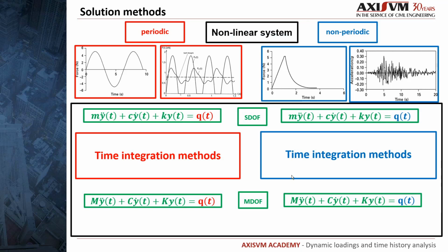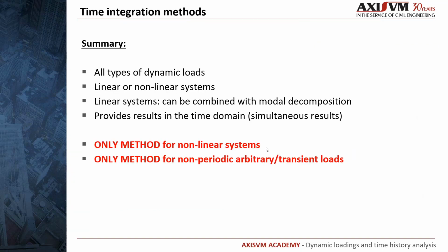If we have a nonlinear system, superposition cannot be used anymore. The only option to solve the equation of motion is the application of numerical time integration methods. A quick summary: time integration methods or time history analysis can be applied for all types of loads, for example arbitrary dynamic loads, and also for linear and nonlinear systems. For linear MDOF systems, it is possible to combine time history with modal decomposition. Time integration methods have in common that the loading and the response history are discretized into a sequence of time steps, so we obtain simultaneous internal forces, accelerations, velocities, and displacements in the time domain.